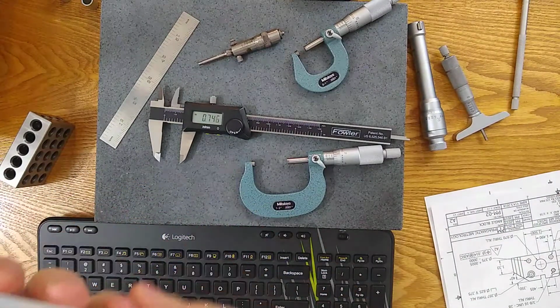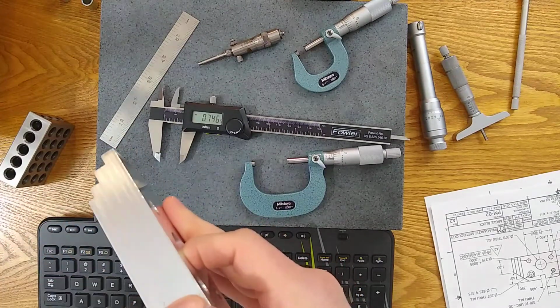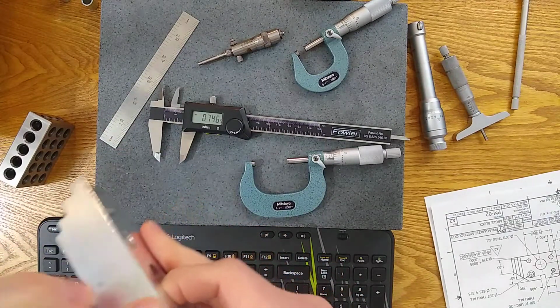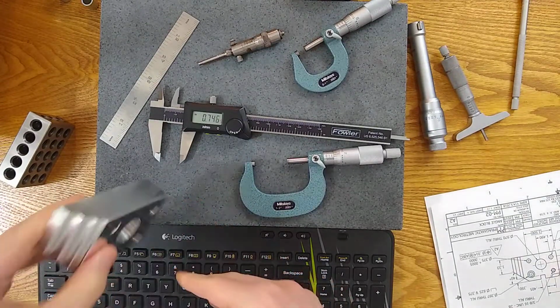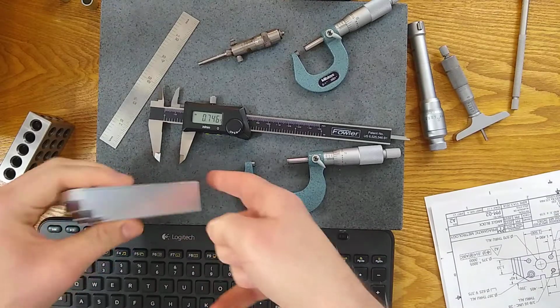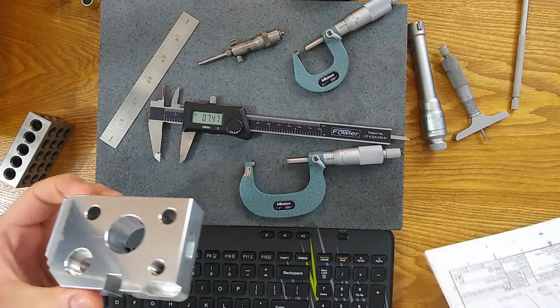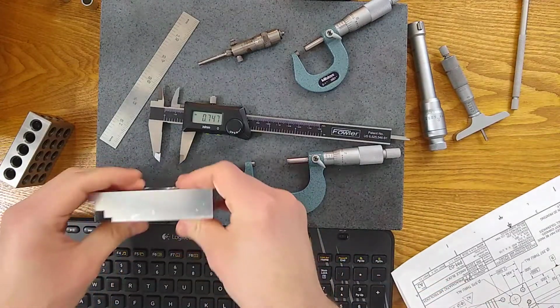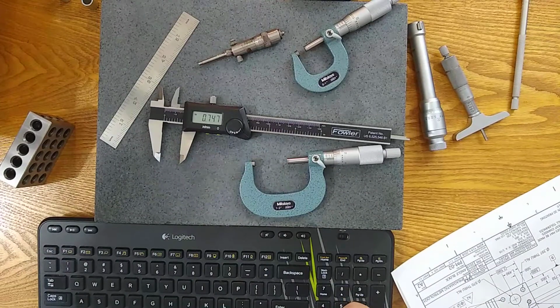You want to take a quick verification. Some verifications you can do: maybe run an indicator and see if there are any issues. Feel it with your fingers. How smooth is it? Do you feel chatter? Run indicators up and down and parallel. These are just quick checks. There's nothing on the print that you're verifying. You're just trying to see if things are flat, parallel, square, and in good condition.